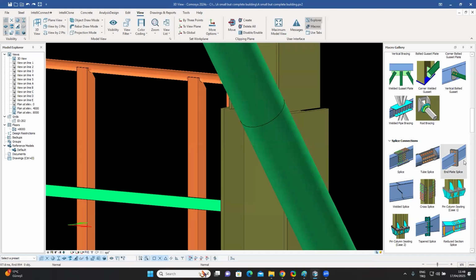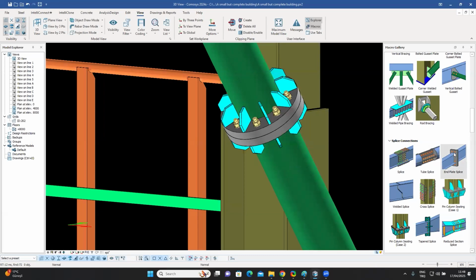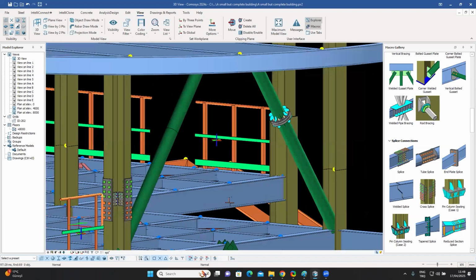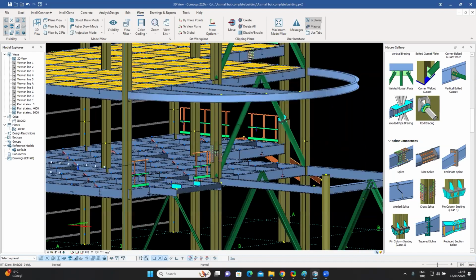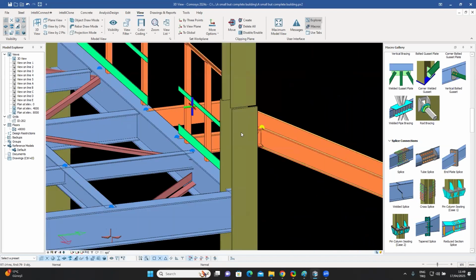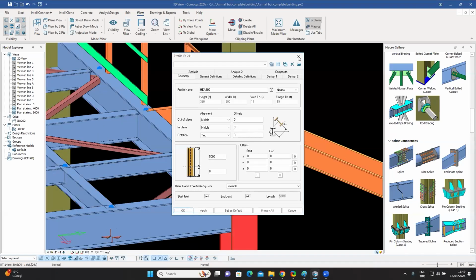Or you could do the classical end plate kind of splice, which is the one on the right over there. This one will also work for rectangular hollow sections as well as for I profiles. Basically, it is an end plate kind of splice. You will need a much thicker end plate, but it is possible and doable. So those are very useful splice connections.